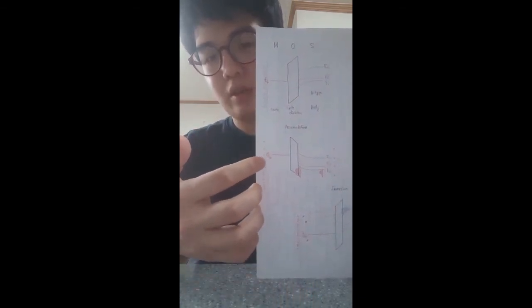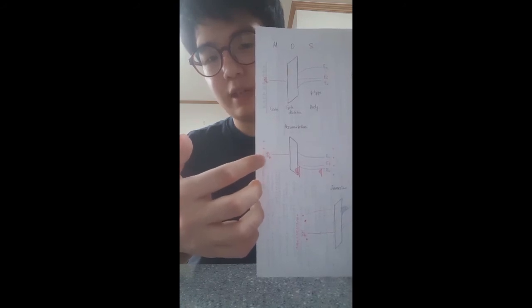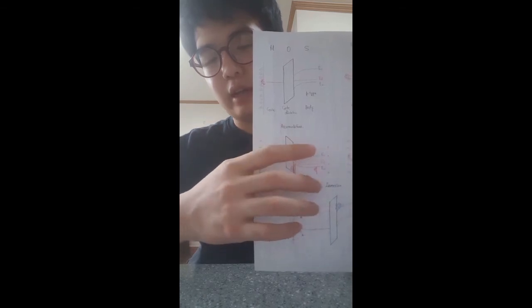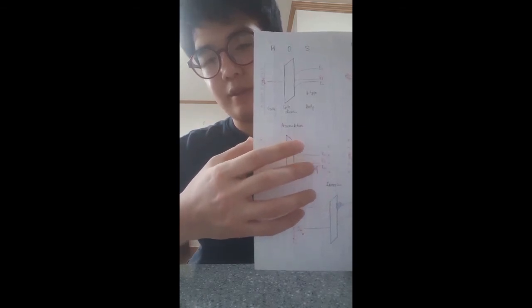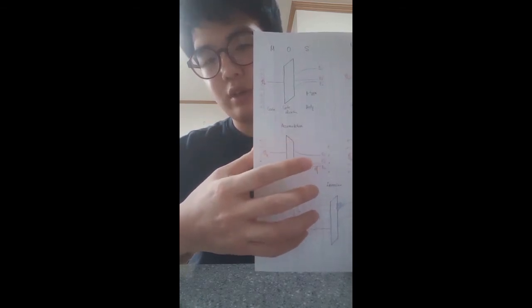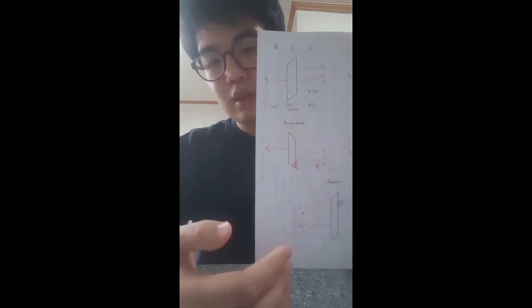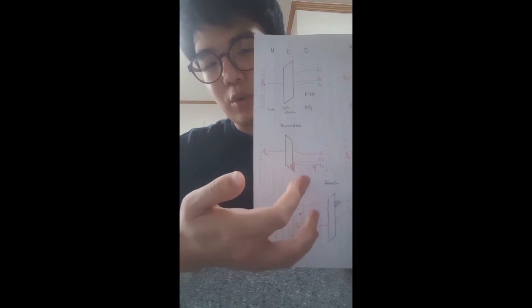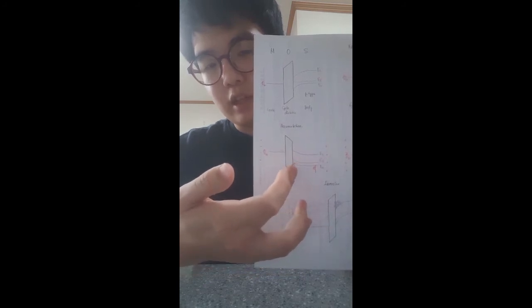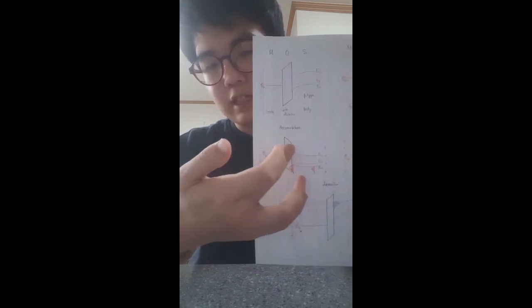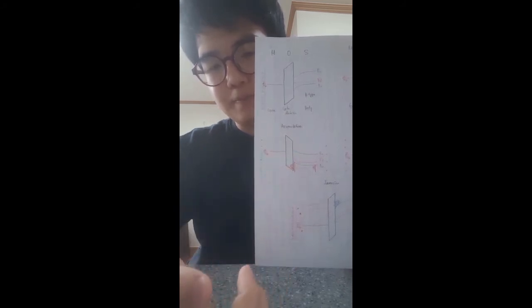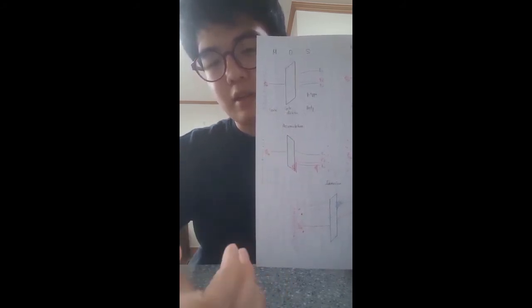Then the work function of the metal is going to be higher than before, and the energy band of the semiconductor will be lower than before. So the majority mobile carrier, the hole, will be accumulated at the interface of the gate dielectric and the body. We call this phenomenon accumulation.